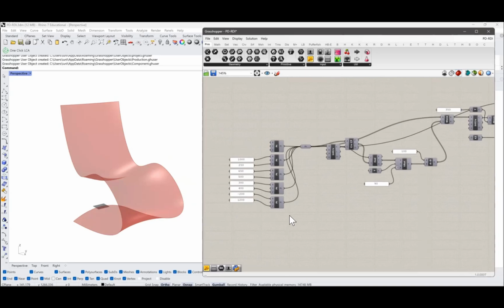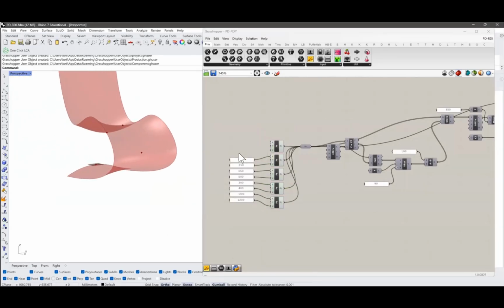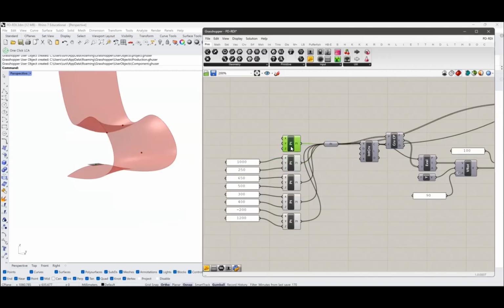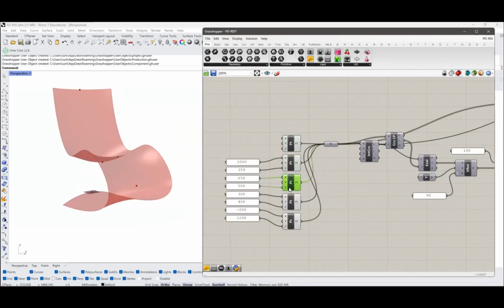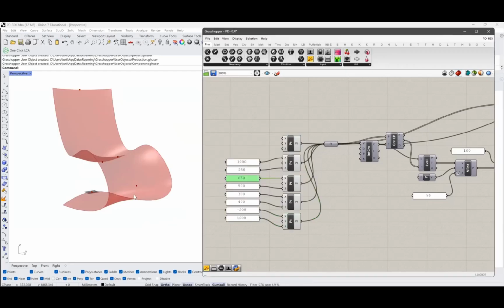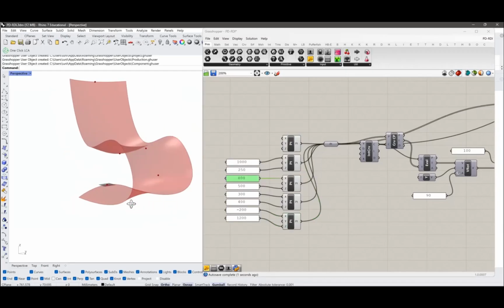We started originally in Grasshopper. We model some key points that are controlling, and then we can control the X, Y, Z of these points. If I click it, you see that I select the representation of these points. Then, for example, if you change some parameter, you have the deformation of the chair.